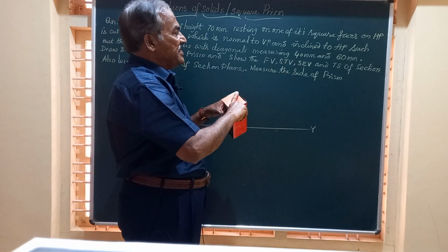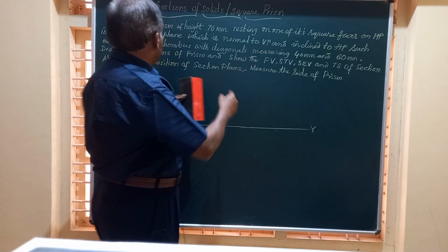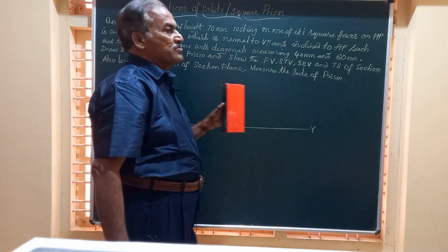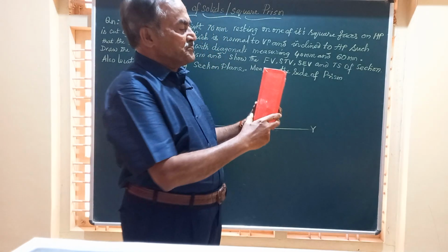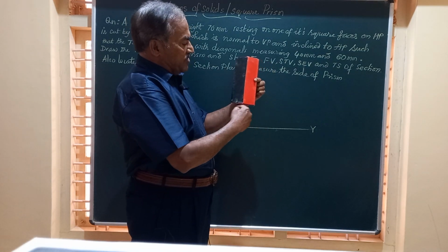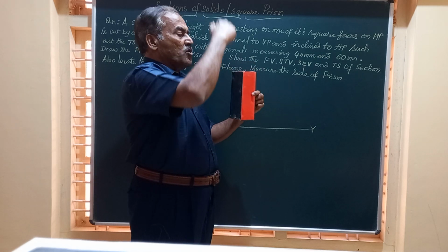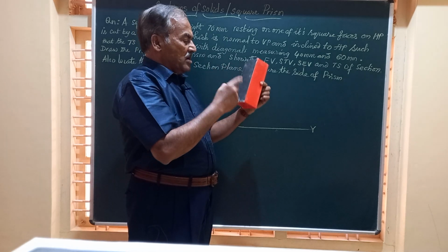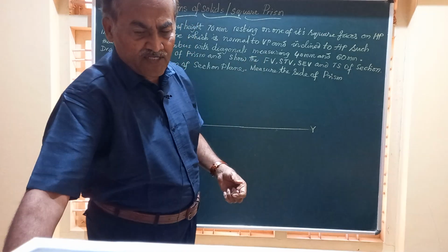This will be 40, and when it is cut at an angle, he has specified the true shape should become a rhombus. So friends, we are going to hold this prism with all the four sides equally inclined to VP and get the top view a square and front view two rectangles. You are going to get it like this.